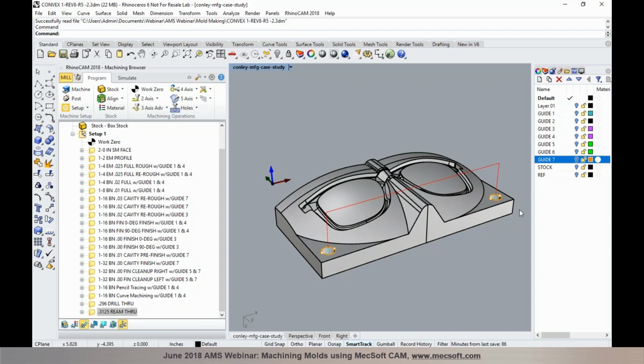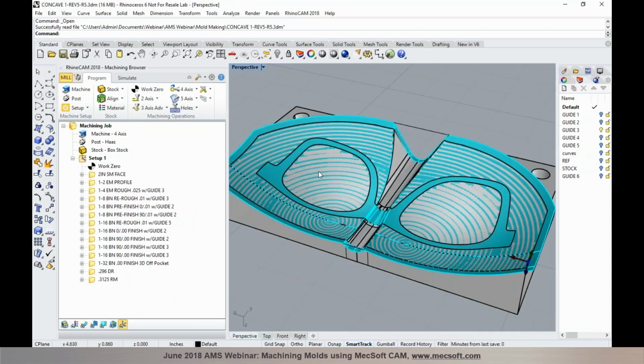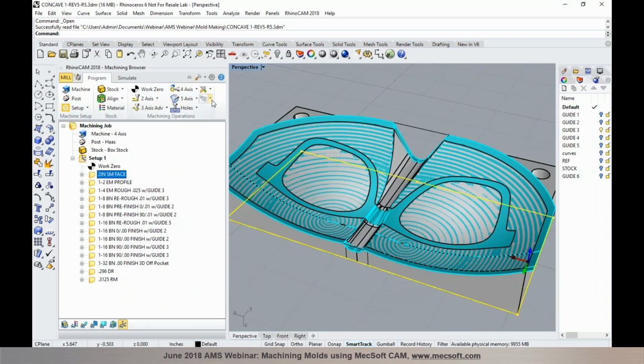Now one of the strengths of our CAM product is being able to take the toolpath that you already generated in one of your parts or family of parts, and reuse or apply them on other parts, where you can actually save these operations that you programmed into a knowledge base. So you can save the workflow of operations like the roughing, re-roughing, and pre-finishing operations to a knowledge base and take those operations into your other model. You can load the knowledge base in, edit the operations, and select the geometries that you'd like to use for programming.